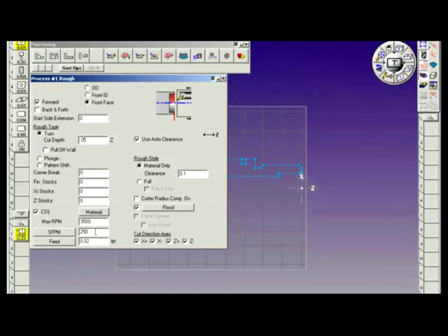Surface feet per minute is the way we program the CSS. Let's go with 1,200 surface feet per minute. It's aluminum. We've got a decent grade of insert. And I'm going to use a feed rate of 10 thousandths per revolution. It'll give me a nice cut on the face of this part.